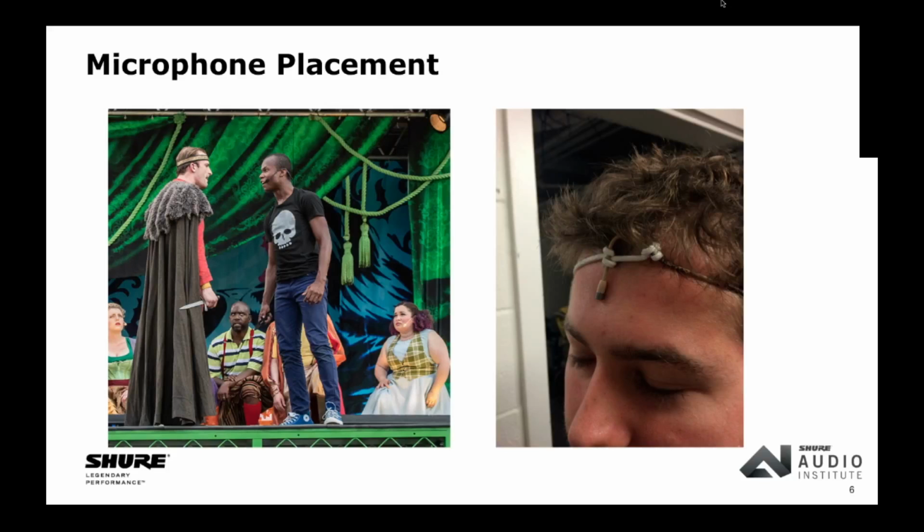Okay. But if you'll notice, the rig does specifically have the lavalier pointed straight down at the mouth. Even though that lavalier is omnidirectional, it still is more sensitive towards the front end of the capsule. Right, particularly for the higher frequencies. Which is the intelligibility. Mm-hmm. So even though it's omni, don't get lazy and assume you can just let it point any old way.